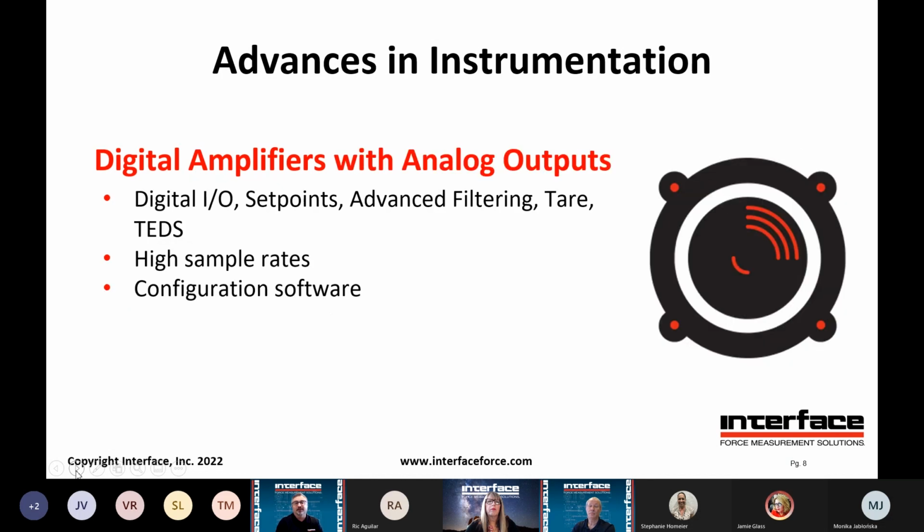Next slide, please. Talked about digital amplifiers with analog outputs. One of the neat things, some of our amplifiers have a wide range of digital inputs and outputs, and our software that comes with them can make use of those as threshold set points or triggers and things, but also they're available. And we have DLL libraries that come with these items where the customer is writing their own software.